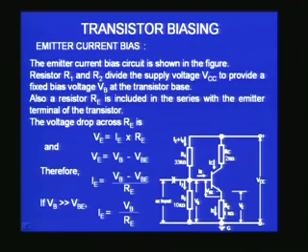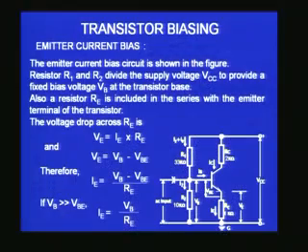But you have another problem in this. Any amplifier, and this becomes an amplifier later on, should have an input impedance, or input resistance, that is the resistance as I look from the input side into the amplifier, that is very large. Why, etc., we will discuss at a later stage, but in principle let us assume the input resistance of a good voltage amplifier should be very high, and that will be ensured only if I choose my R1 R2 values very large. So now here I have a problem.